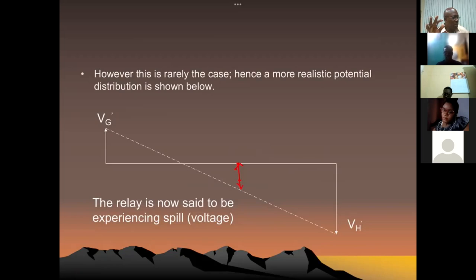So it means, therefore, that there has to be not just the presence of a resultant current through the relay. All right, we have to move beyond that. We can't just say, well, once the current is non-zero, that you will have a trip, because you will have a current flowing by virtue of the fact that the CTs on either side are not identical. Are you with me?